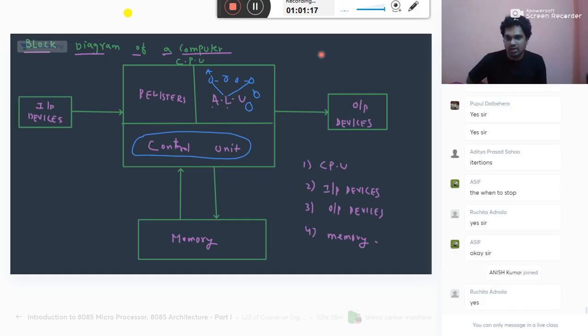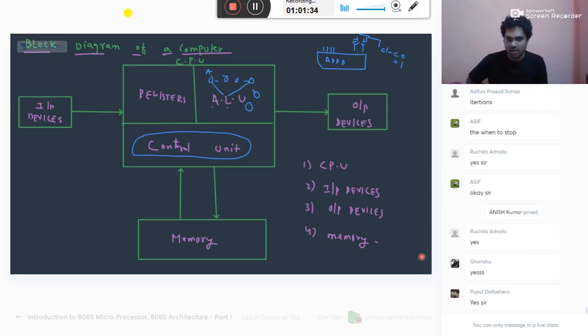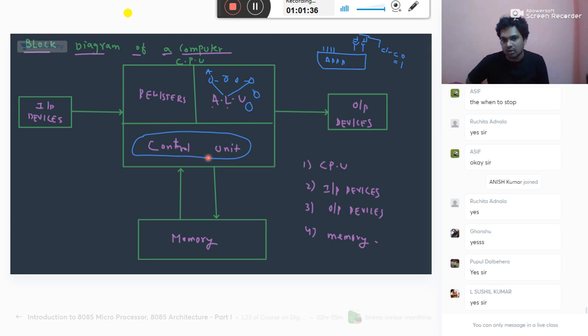Do you remember this or not? You have an adder circuit. You give the first input as it is. The second input is given via XOR. The XOR input has one name, what? Control signal. When control is 0, addition. When control is 1, subtraction. Same here also. The computer will give the necessary control signal such that the required operation is done by your computer.